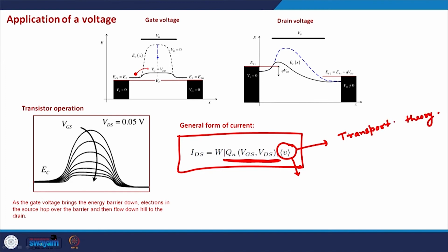If the electrons are scattering with particles in between, we will need to take into account the scattering of electrons. If the electrons are going directly from the source to the drain terminal, as we have already seen in a ballistic MOSFET, this velocity will be known as the ballistic injection velocity. So, understanding this velocity is the subject matter of electron transport,